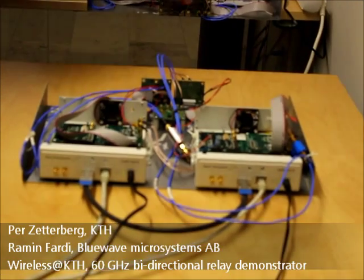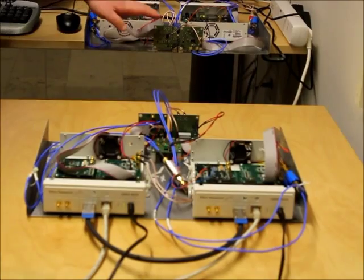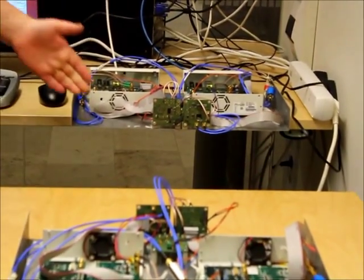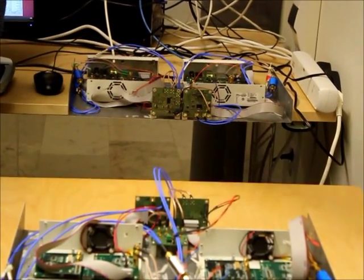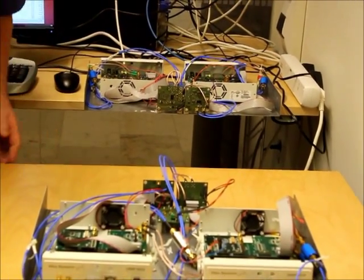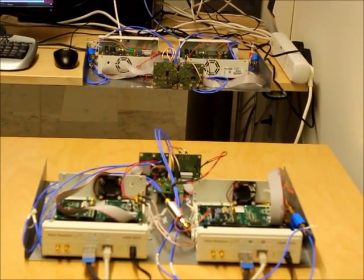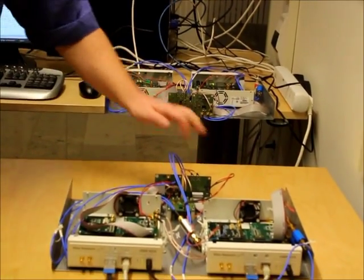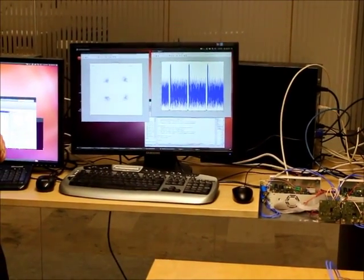So here we have two transmitter boards and here we have two receiver boards, and the most important component is a Hittite chip that does the up conversion in the transmitter and down conversion in the receiver. These chips have an inbuilt antenna with about 90-degree opening angle, and now we have one polarized in this direction and one polarized in this direction. But right now we are just transmitting on this board and receiving on this board. So now it's the transmission right now.